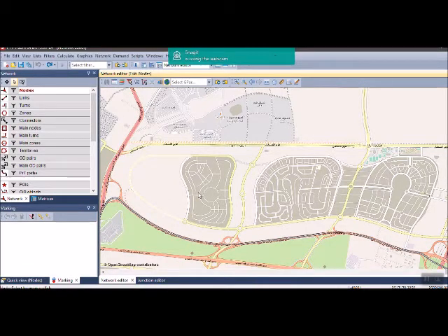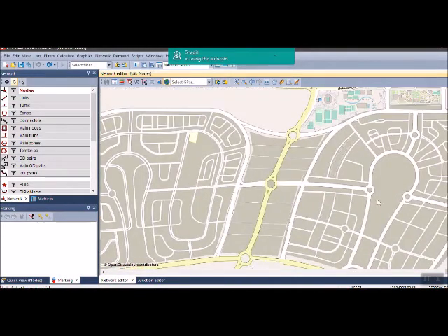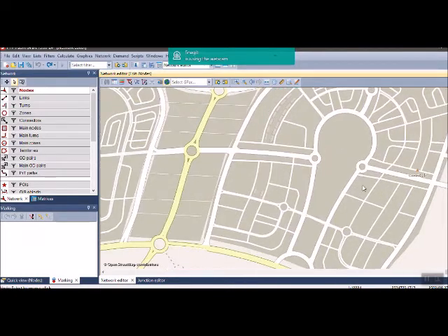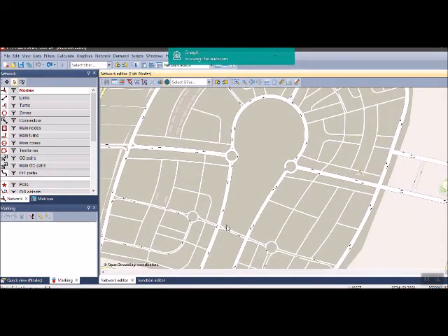Another important thing that you should know is that each zone should be homogeneous in its characteristics. For example, if we are going to have a real life example like this, you should know that dividing the zones depends on their characteristics and they should be homogeneous in their characteristics. For example, if I have a commercial area like in this one, I can consider this one as a zone.